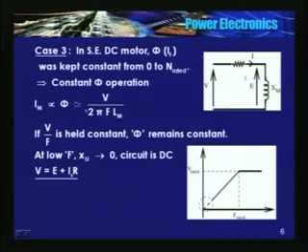Okay. See in this equation, I_m is proportional to flux, and this is approximately equal to V, the supply voltage. Maybe in the previous equivalent circuit I must have called it a V_s, okay, divided by 2 pi f into L_m. Okay.